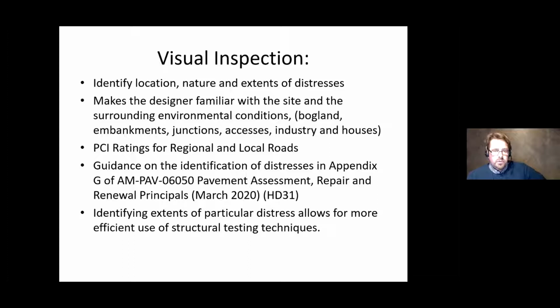There's a huge range of stresses which can be worked out, which you'll all be familiar with, in terms of rutting, raveling, different types of cracking, delamination and potholing. There are excellent photographs of all these and how to identify them in the back, Appendix G of HD 31. So I won't show you the images there, but if there's time after the questions, I might. But it's worth going back and referencing and getting familiar with before you go out on site. It's quite a hefty document to carry on site, but it would be worth doing.